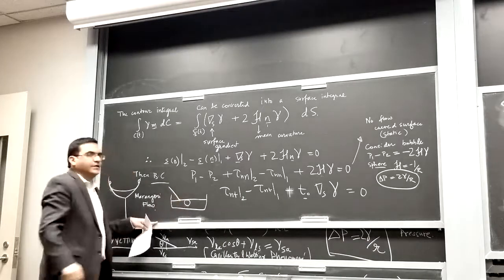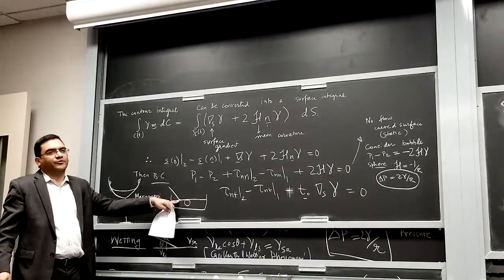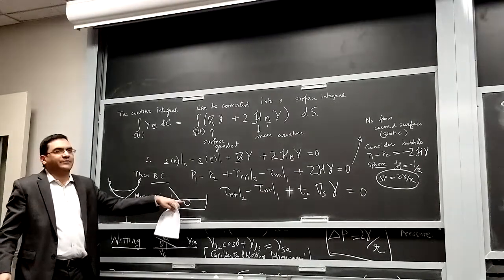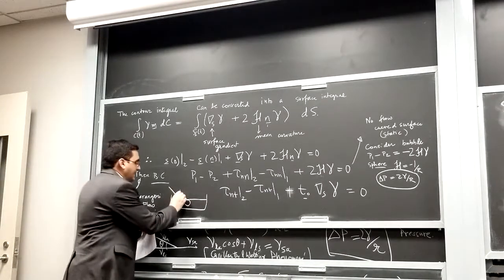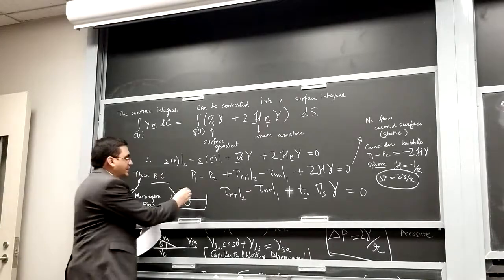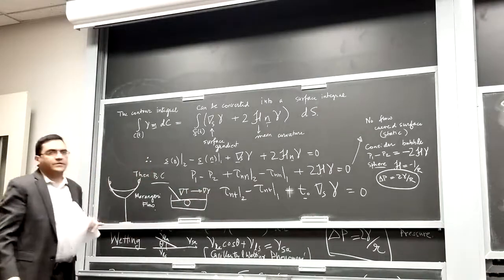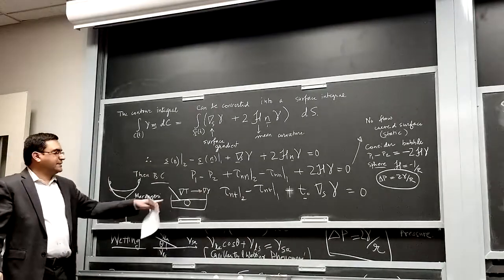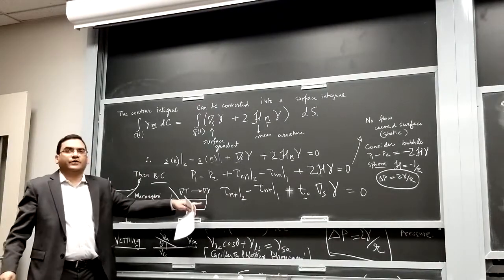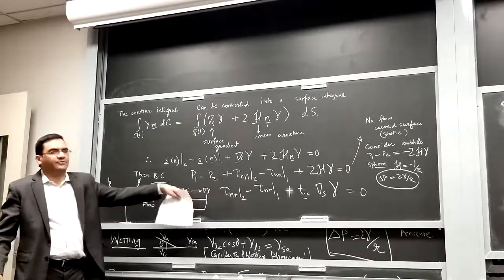So if you use an IR laser that locally heats the fluid, then that causes a temperature gradient. And because surface tension depends on temperature, this can create a surface tension gradient, and then that actually drives a flow. So my first paper is all a study of thermocapillary flows done in this way.